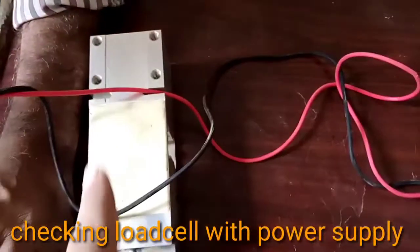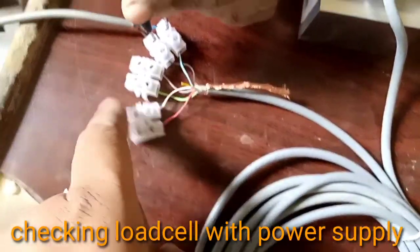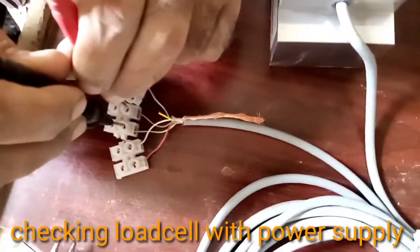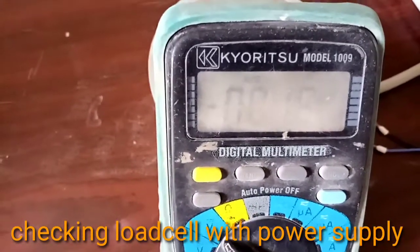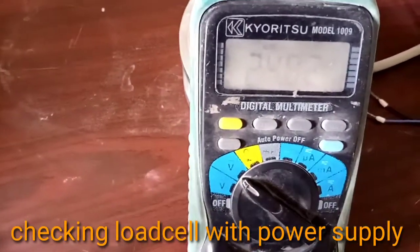Now you can also check its excitation wire, also 24 volt present. If there are 24 volt present, then our load cell is 100% okay. Now you can check the gray and green wires. 24 volt is also present here, like this one.